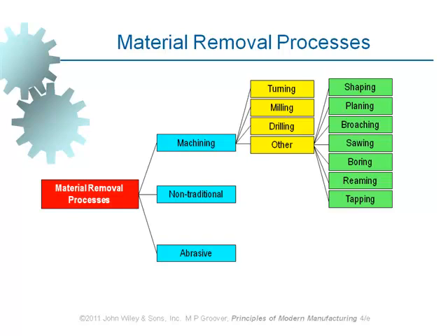Do we know what reaming is? Reaming, what is it? It's similar to drilling. A different type of tool is used when a hole is made, but its dimension is not accurate. When you make the hole with a drill bit, you make a hole which has a dimension close to the final dimension, but it's not accurate, it's not precise. And also the surface finish of the hole is not fine.